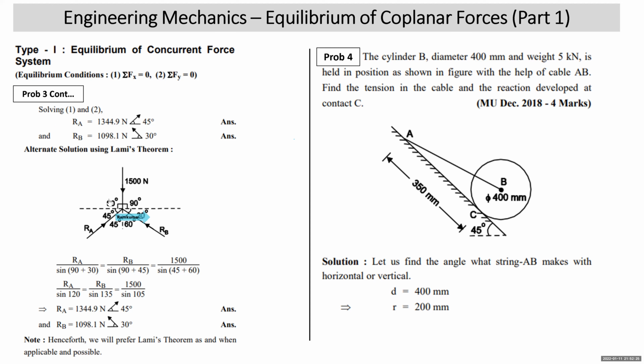I wrote this is 90, 90. Now, this is the fit case to apply Lami's theorem. What is the essential condition to apply Lami's theorem? Lami's theorem states that if three concurrent forces are in equilibrium, then Lami's theorem can be applied, but you should make sure that none of the angle is more than 180 degree. You can see that there is no angle between the two forces which is exceeding 180 degree. So all angles between the two forces are less than 180 degree.